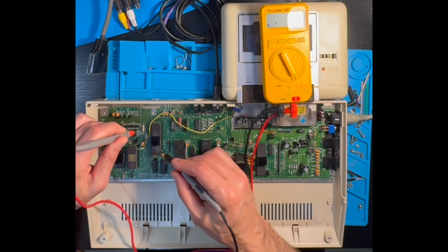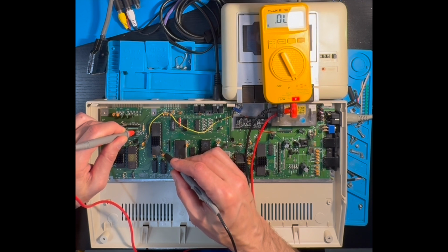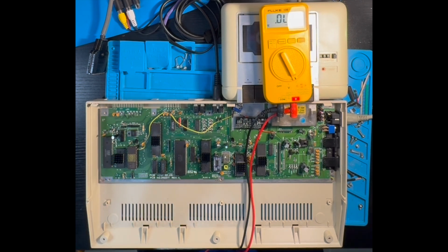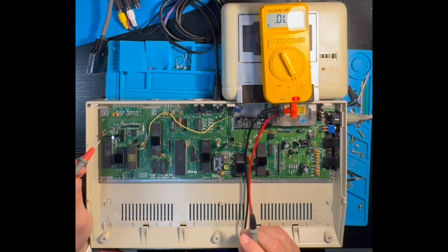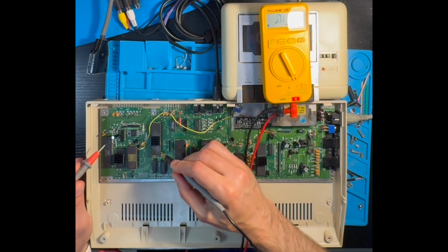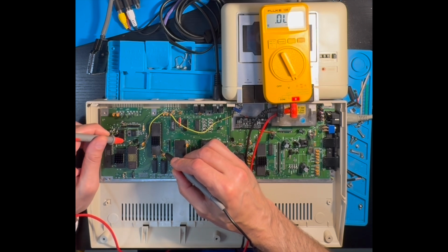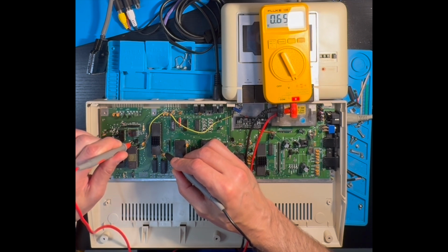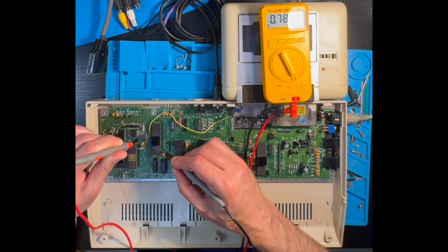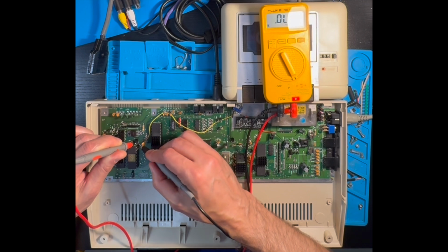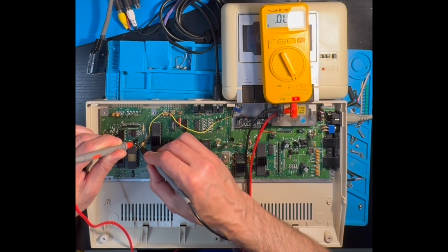And now I'm going to look on the other side from the CPU. I'm going to try to see if there's a break somewhere in there. So somewhere between the circuitry of the CPU and that little port, there's a problem. And this is what I'm trying to figure out at this point. What's going on with it? I can see it's coming here, so it's going through that little resistor. And I'm starting to think this transistor here may be bad. But that's a part that I'm starting to think about. Is that a problem right there?